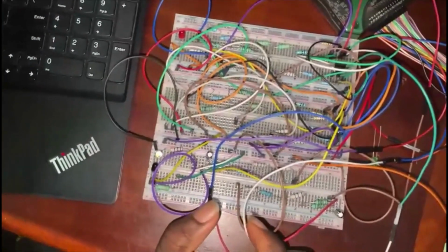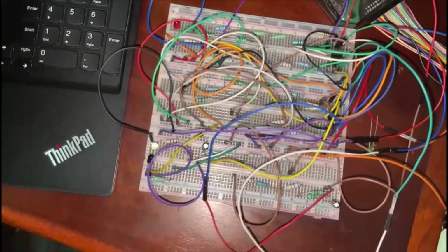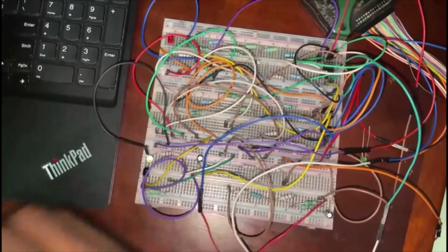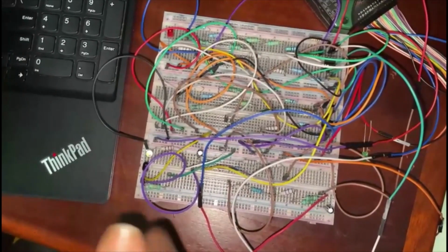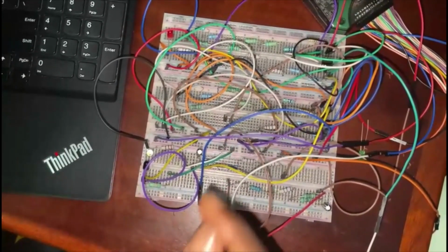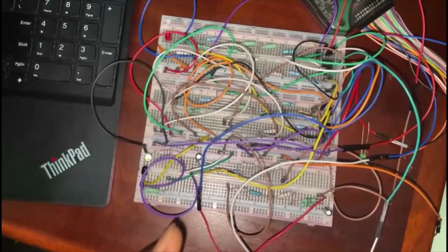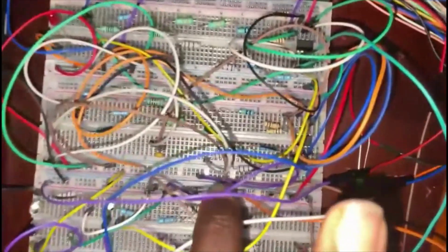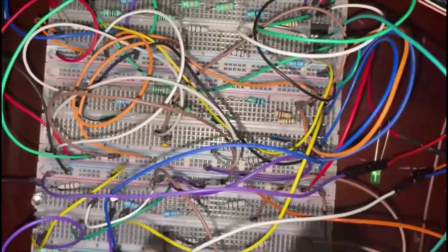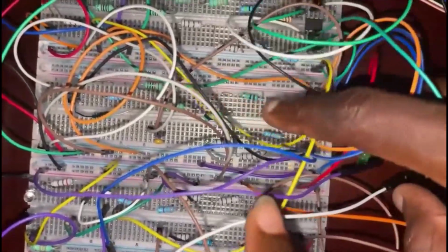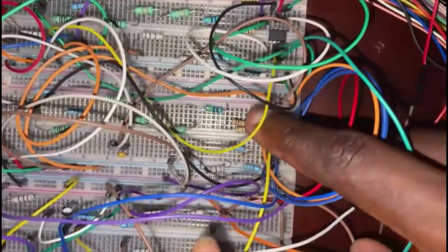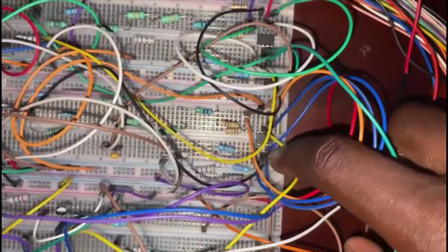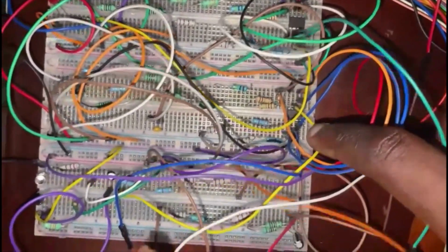So literally we used a passive filter here, which is a high pass filter, because we want to filter out the DC noises to pick up the heart pulse, which is an AC signal. Using that, we have to magnify that small heart pulse using this first op-amp here, which is an active filter that has a magnification of 101, and that's active filtering. In other words, it also does further filtering of the AC signal that we have in to give us that particular heart pulse.